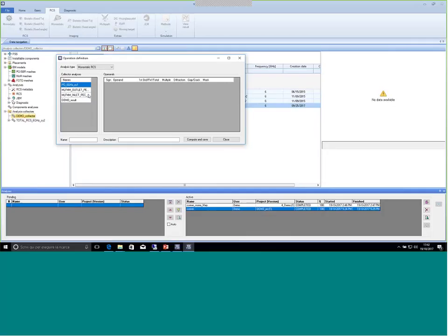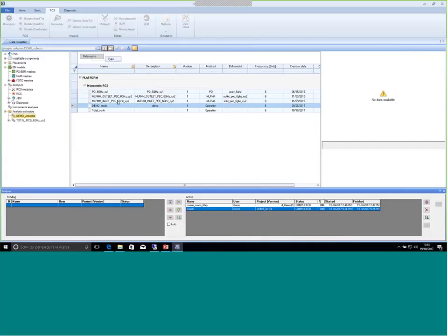And let's see how I can do that. So I can put here all this contribution, and I can select which contribution I want from each one of the simulations that I'm considering. For example, for PO, I can consider the first order and also the diffraction from edge or wedge, and eventually the contribution from gaps or cracks. For a full wave method, of course, I will consider just the full wave contribution. And finally, I can save the final result like total contribution. Compute and save.